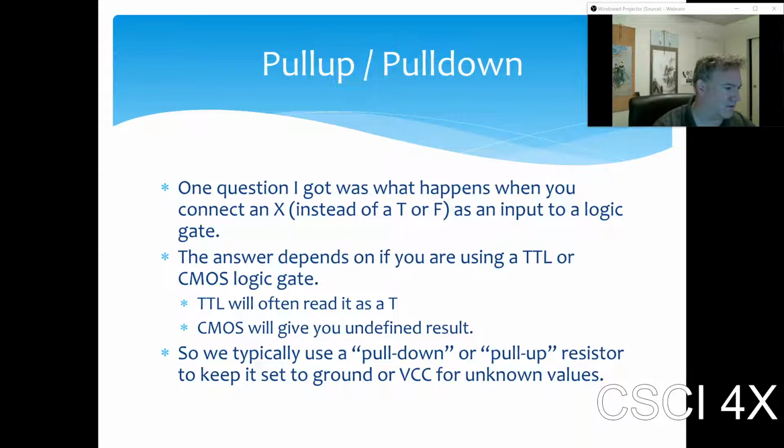Comparing a 0 result versus unknown. So if you try reading an unknown value, if you're just looking at a logic truth table, who knows what you'll get, right? But in real life, the answer depends on whether you're using what's called TTL or CMOS logic gates. If you're reading TTL, it'll typically read as a true if you try reading from a floating gate. And CMOS, who knows what it'll give you.